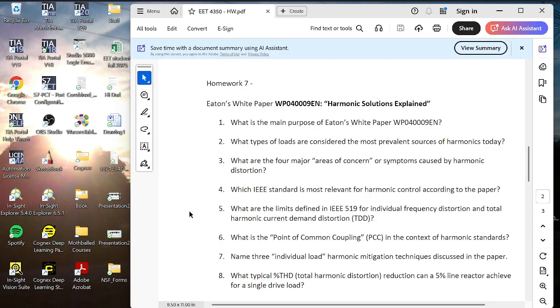How close is close enough? Close enough to pee on it? No, you can't. In a dewy, heavy, misty kind of condition, it'll jump about a foot per thousand volts. So if it's a 10,000 volt system in there, you want to stay about 10 feet away. Okay? You don't want to get close.